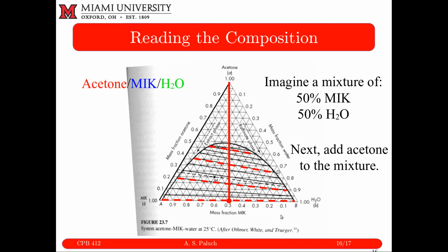Okay. What happens though is as the concentration of acetone increases, my tie line becomes shorter and shorter, and I begin to increase the concentration of water in that extract phase. So I not only suck up acetone, but now I'm going to suck up water. And so up here, now my mole fraction of water is up to 0.5 mole fractions. Okay, so this is problematic.